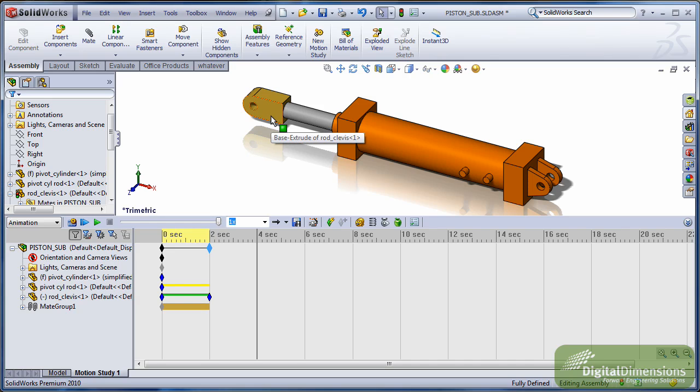If you need to do a rotation and a movement, you would need to actually do your movement and then click out, go back and do your rotation. It doesn't matter if you do rotation first and then movement, or movement and then rotation, but you do have to do them in two steps, going in there a second time. The other thing about rotation is you do need to do increments less than 180, because if you do 180, it could go clockwise or counterclockwise.